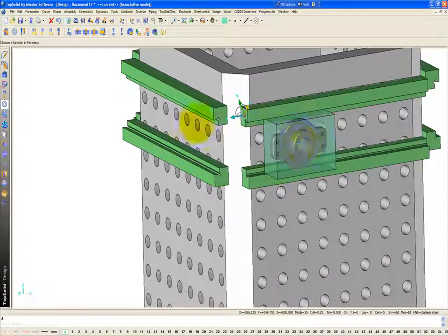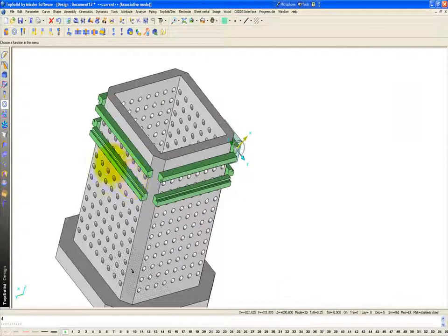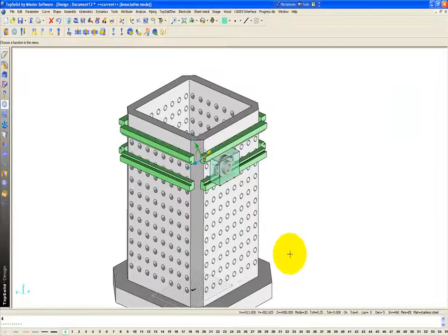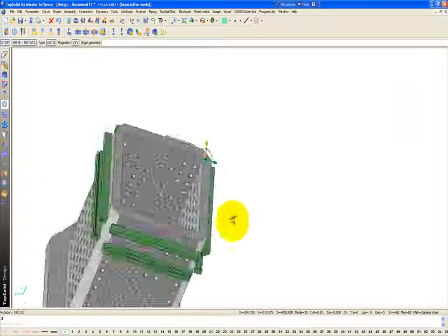Now, this is fine. On two sides of this tombstone, we're going to machine the first side. But on the back side and this side, maybe we want to machine the back of the part. Okay? So we're going to go ahead and lay that out as well. All I'm going to do is say include standard, part to machine again. I'm going to dump it back here.